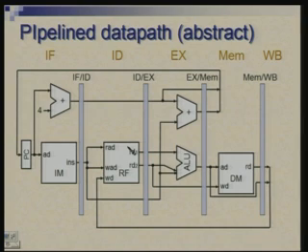So, the whole data path is actually very clearly divided into stages. You can label these as IF stage, instruction fetch stage, instruction decode or register fetch stage, execution stage, memory access stage, and write back stage. So, write back is actually happening into this register file, but it is a stage which is afterwards. So, that is how I have written.